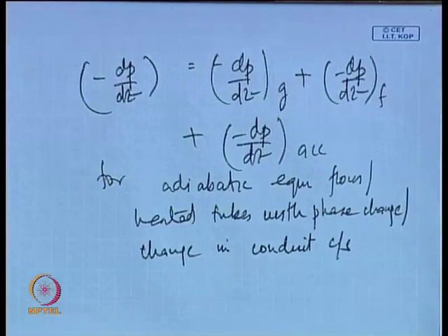But what will be the expression of this acceleration pressure gradient, how many terms will it comprise? That will depend on what factors contribute to the acceleration pressure gradient. If there is an area change accompanied by heat transfer, definitely it will comprise the requisite number of terms. Under normal circumstances, it will just have one particular term. Why?